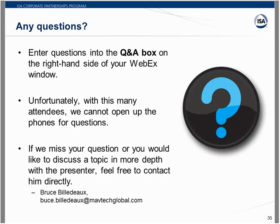A lot of customers have a single computer where, if you need to bring something in on USB, you can bring it in there, or you take it to IT, let them take the information off of that, and then bring it down into a safe place on the network where it can be grabbed for the ICS network. That's probably the best because they're more familiar with the ongoing differences in threats on a USB than your ICS people, and with keeping that software updated. So for me, I suggest sealing the PCs and closing off all the USBs is the best approach. I also feel that all unused ports on switches should be locked out and password protected. It's usually a small, low-changing system, so there's no reason not to lock out everything you can.